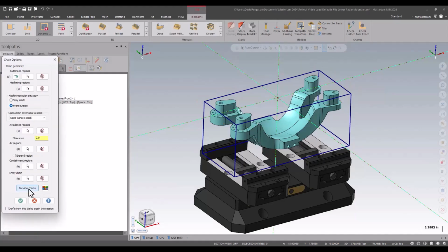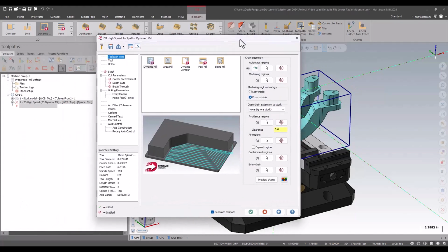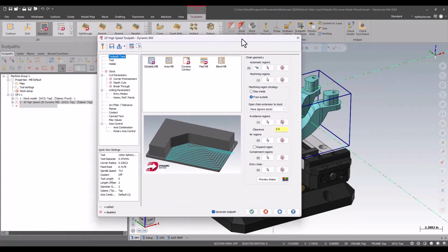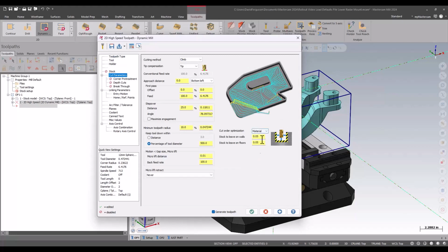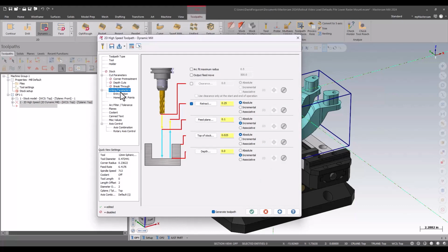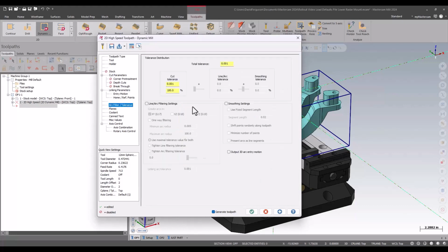And with this one, I just created a brand new one. I didn't import a toolpath with my settings in it. I created a brand new blank toolpath. And so this toolpath doesn't have, for example, corner pretreatment turned on. My depth of cuts is disabled. I don't have my arc filter enabled, right? The stock to leave isn't where I like it. Nothing is where I want it. And that's why normally I would have gone through and imported, right, an existing toolpath. So I don't have to sit there and go and change each of those dialogues independently.